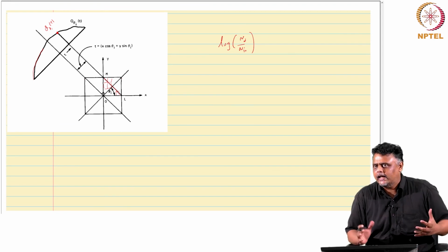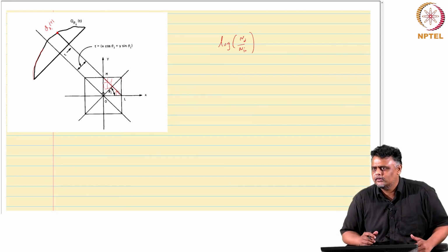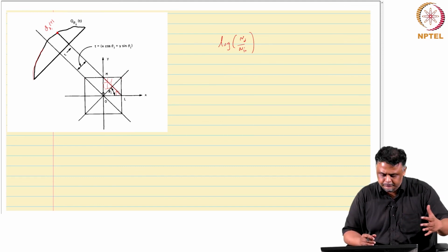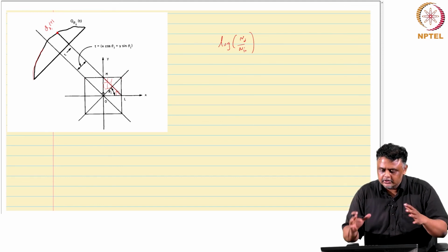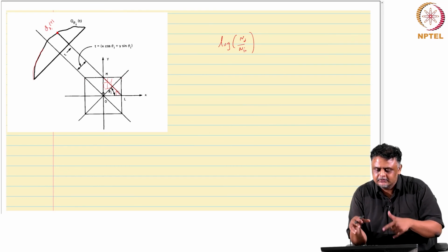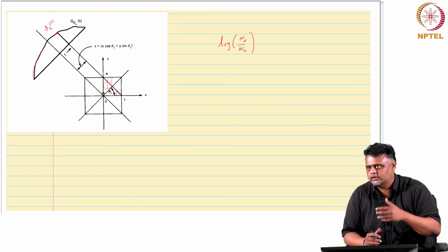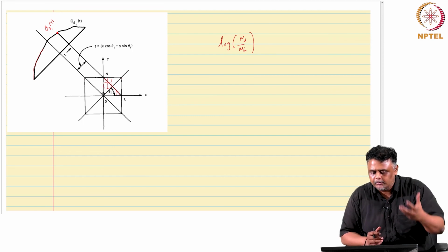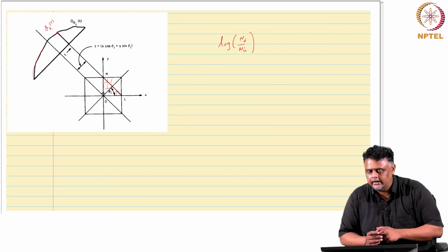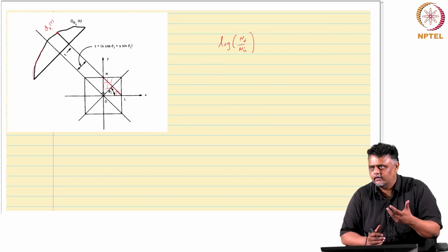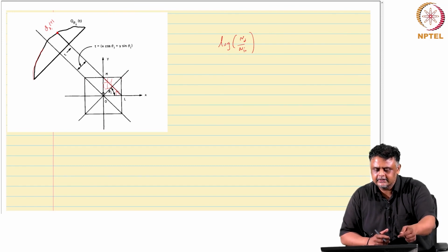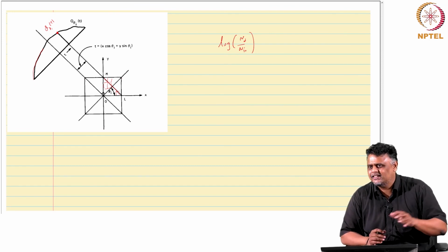There are many different types of filters, basically to remove high frequency noise and some of the spurious noise which can come, and this filtering is also essential because you are adding over all the projections, so the filtering helps. It actually comes out of the derivation, but I will not go through that. You have to take the raw projection, which is this log data, and filter it with a digital filter. You use a fast Fourier transform filter and then take that filtered projection and back project. So, this is a typical algorithm.